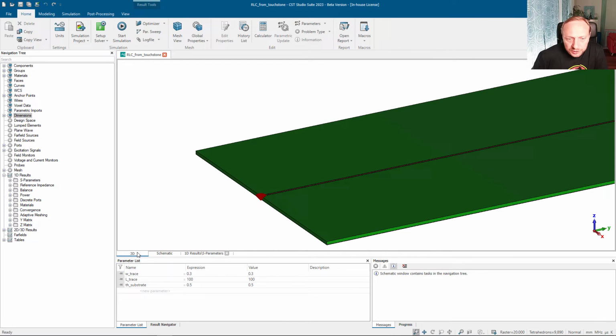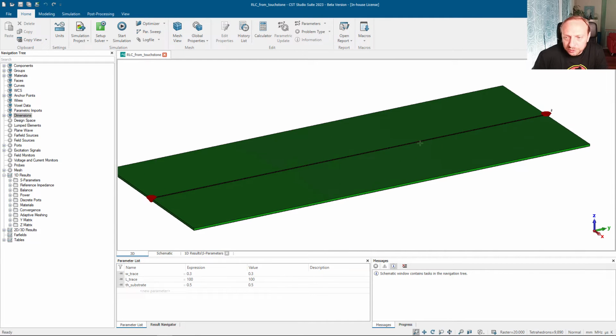Now imagine you would like to, for example, understand what is the resistance of this setup. First thing, obviously, is we cannot extract from our S parameter values just the resistance of the signal trace. What we can always get is the resistance or the inductance of the loop, but just for the trace itself, that's not possible, because the S parameters are always defined with inner and outer, right? So you reference your signal trace to the plane, and you do the same on the other side.